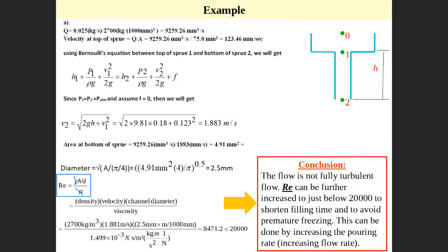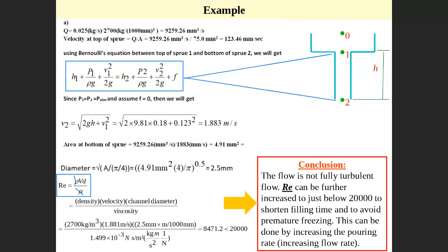We need to apply the Bernoulli equation because I don't have the head of point 2. Then we apply Bernoulli between point 1 and point 2. When applying between them, the pressure terms are zero, to avoid aspiration, so P1 equals 0 and P2 equals 0. Friction we will ignore, as he said to ignore friction. Then you have in the equation H1 and H2, and V1 and V2.